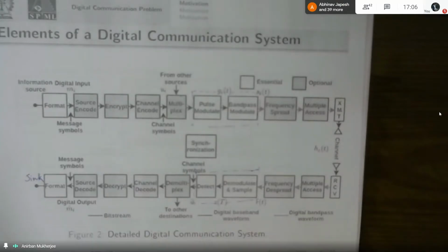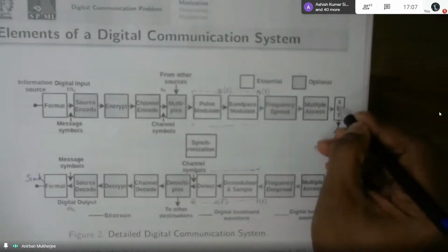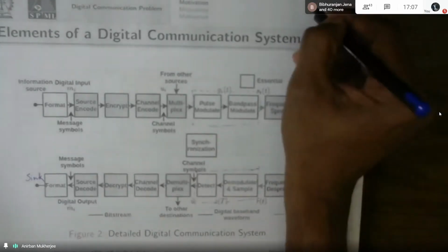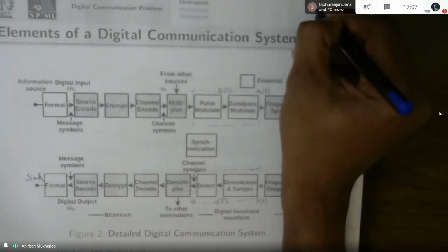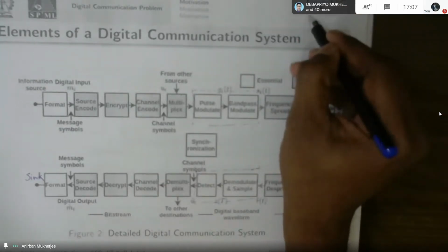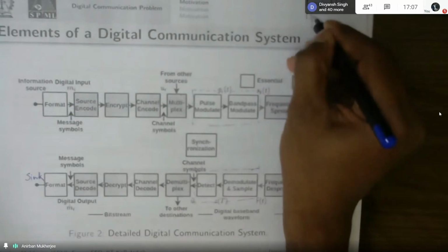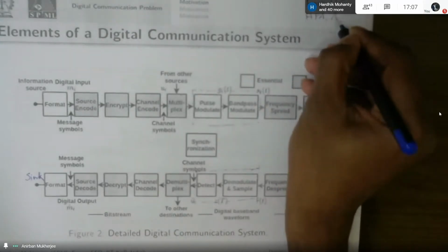And for wireless applications, mainly we talk about wireless applications. The transmitter, this XMT, consists of a frequency up conversion stage to a radio frequency, some sort of 2.4 gigahertz level that you are transmitting. There you have the band, a high power amplifier and an antenna. So inside this XMT you have frequency up conversion, an HPA and an antenna.